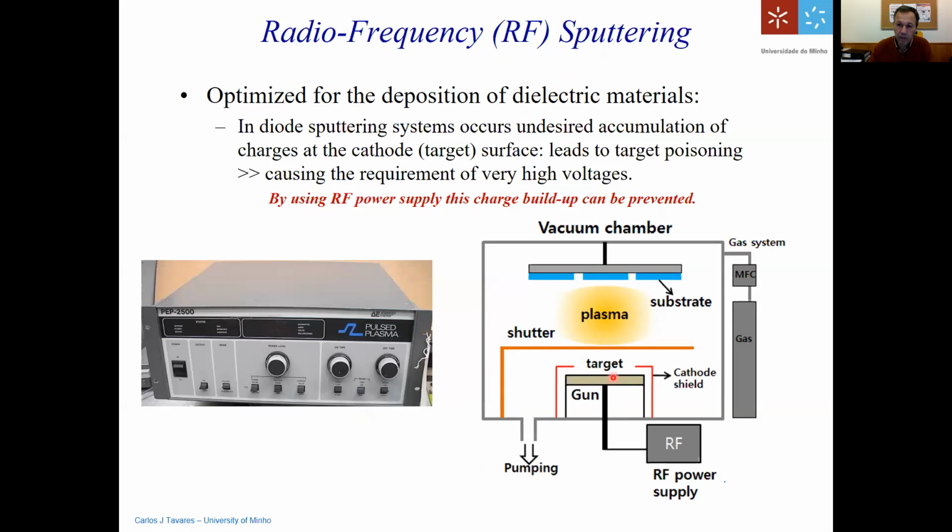So if you want to use a reactive gas in the process, you have to have another bottle for the reactive gas, for example acetylene to provide carbon, or nitrogen, or oxygen. And for each of the gas bottles, you have to have specific mass flow controllers, calibrated for the type of gas that you're going to use and with a range of opening of the solenoid valve appropriate for the inlet amounts, which we normally say in SCCMs, or milliliters per minute, that you want to introduce into your system.